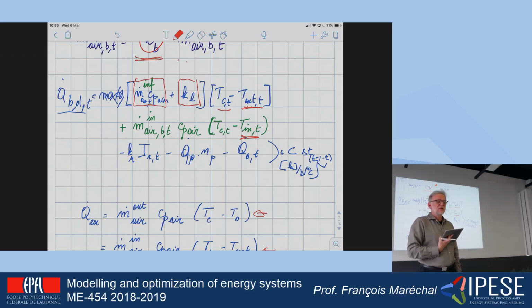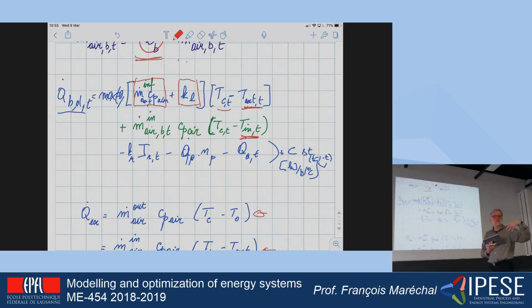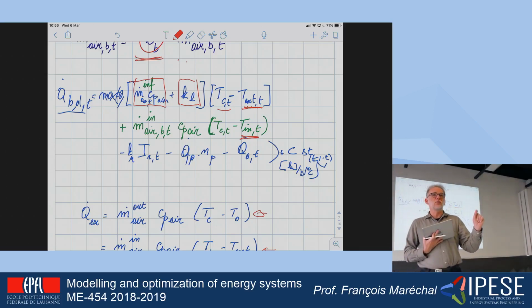Okay? So, what we have made by doing this is transforming an idea into something that can be evaluated and that translates into a profile of heat load that is needed by the system. Okay? And the heat load profile, so as a function of the temperature outside. Okay? And something that I have indeed used, which is the trick, is that at the end I do not need a lot of information.